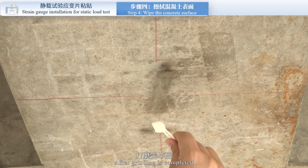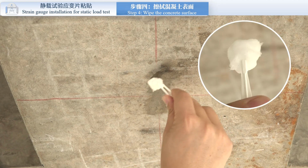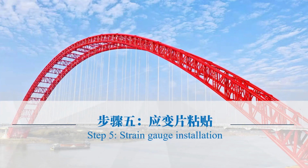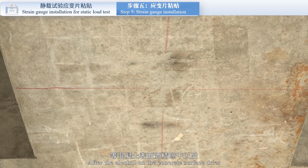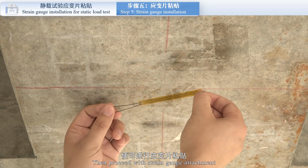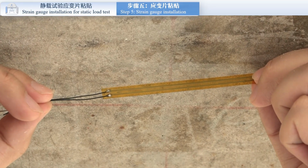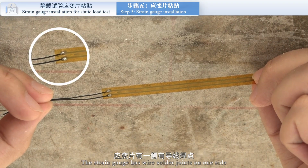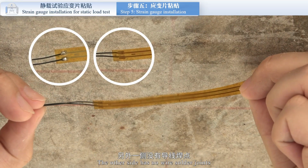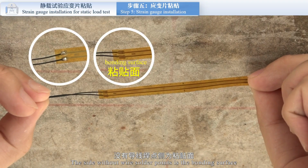After grinding is completed, use alcohol and cotton to wipe the concrete surface until no dirt is found on the cotton. After the alcohol on the concrete surface dries, then proceed with strain gauge attachment. Identify the strain gauge's bonding surface before installation. The strain gauge has wire solder joints on one side. The other side has no wire solder joints. The side without wire solder points is the bonding surface.